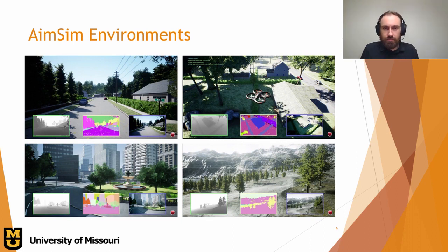So to get better looking simulations, we turn to AirSim, which is built as a plugin for the Unreal Engine. This means that we can load up just about any environment map or asset pack from the Unreal Marketplace and use these as simulation environments. We can even fly around in cities or places where it might be difficult to actually fly a real drone. AirSim has a direct API that we can access with Python, and it can also work with ROS to control the drone and send back images and sensor data.